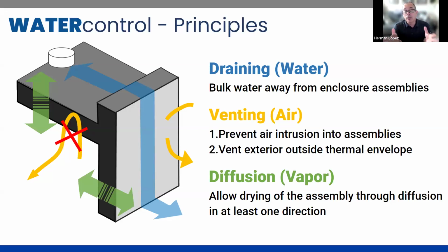In the wall assembly, when there is a failure, when there is moisture that's made its way in, especially moisture vapor through air infiltration, it doesn't present until a disaster is happening. If you have some organic growth on an area of the wall or some efflorescence happening on some masonry, you likely have a disaster happening on the other side, because much like it takes a while for it to get in there through diffusion, it takes a while to present itself and let you know that there's a problem.